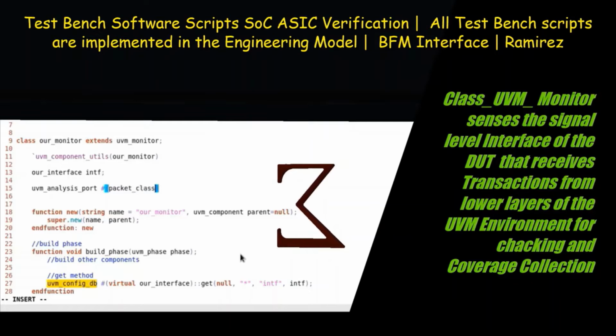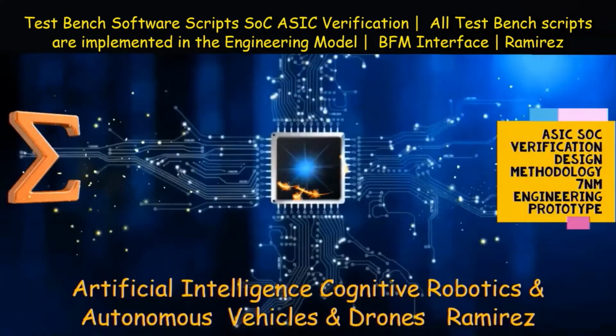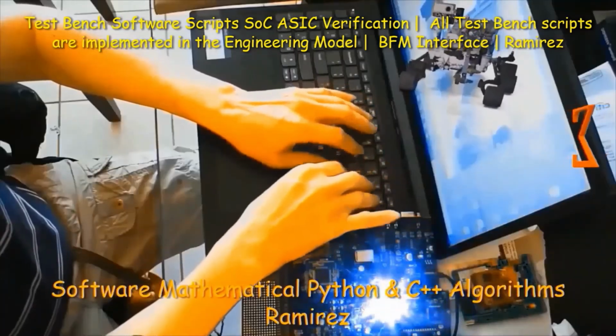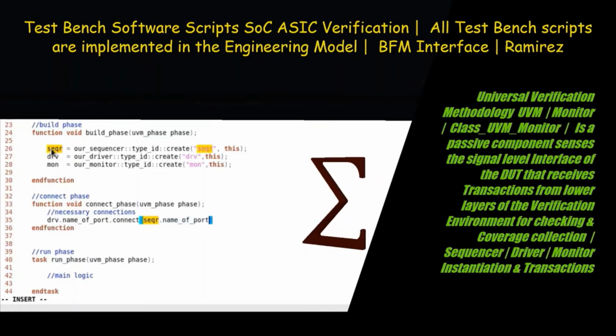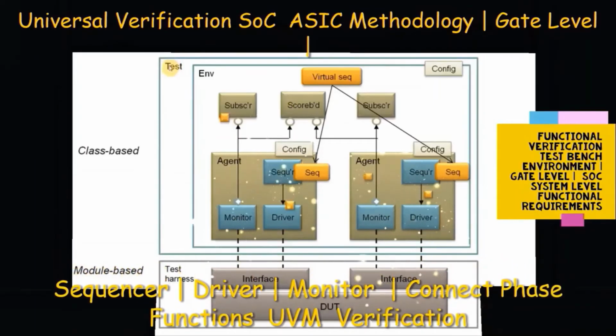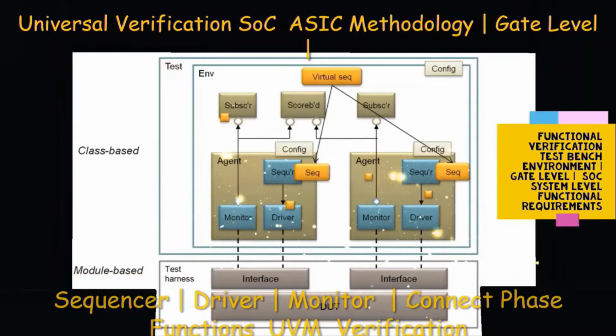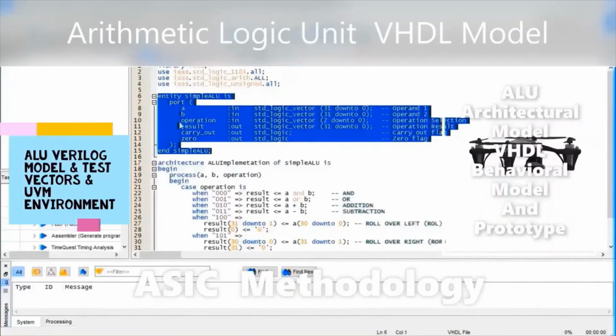The virtual interface within the top level configuration object is set to point to the BFM interface within the test harness, that is top_HDL_th.bus_BFM_0. This is a full hierarchical reference to the interface instance of bus_BFM_0 within the top level module.